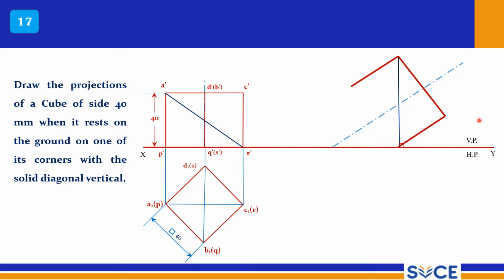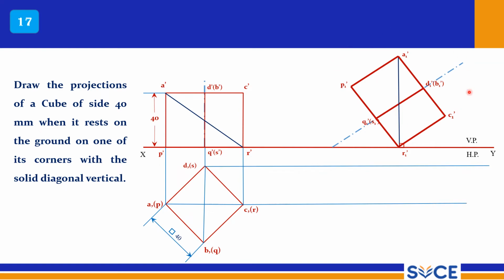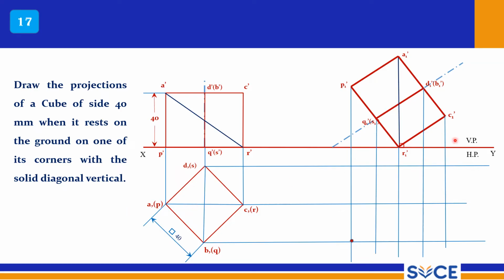Similarly, since you have a drafter, to this line you can draw a parallel line, and to this line you can draw a parallel line. You will get the P corner as well. Now you draw the remaining lines, and the axis line can be drawn now; it will be convenient. Now you have reproduced this view, and you have to draw the projectors from the simple top view and tilted front view. So mark the points.